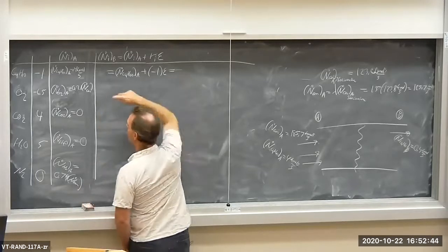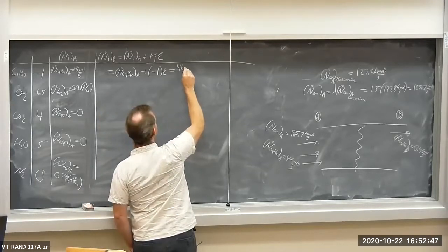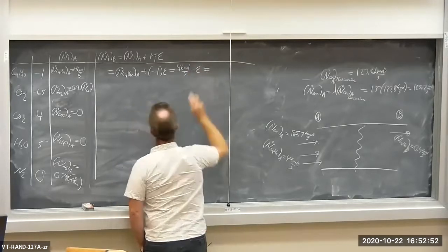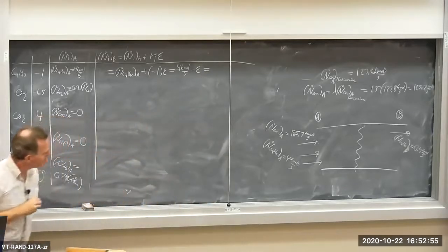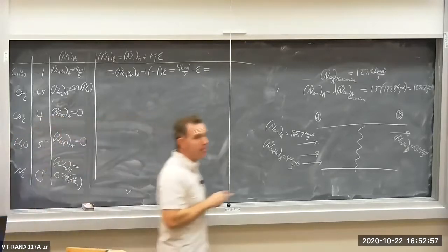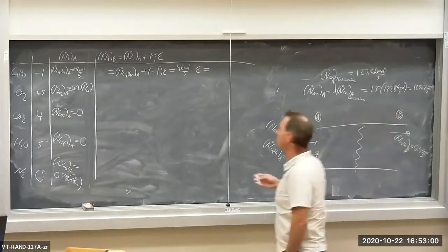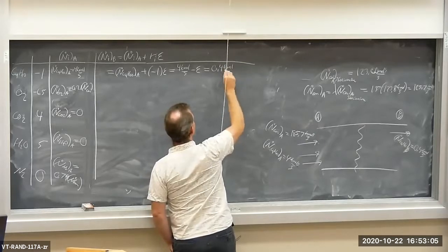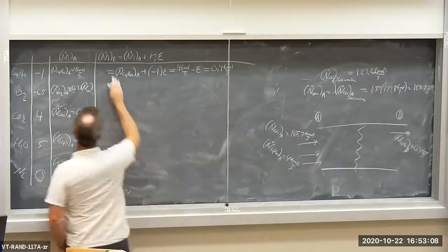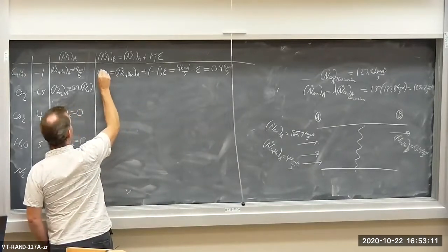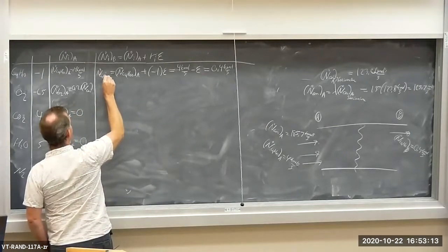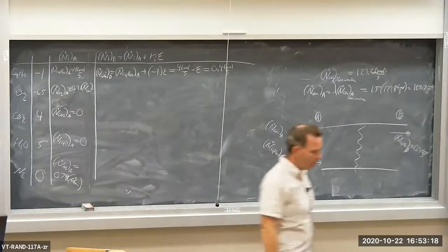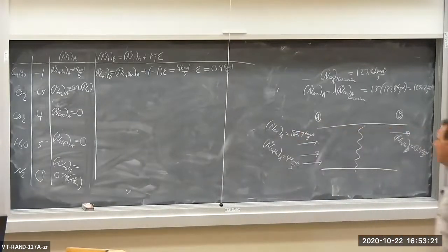And by the way, plugging in 4 kilomoles per second minus the reaction coordinate. The outflow rate of fuel, it's unburned fuel, is 0.4 kilomoles per second, n dot C4H10 at the outlet.